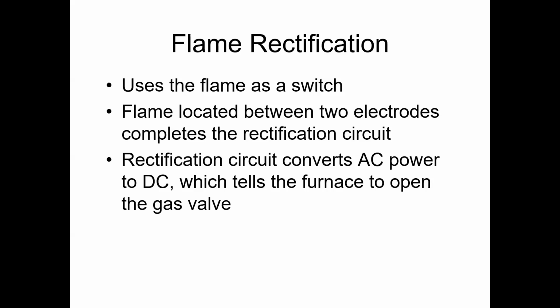These are used with HSIs. They're used with direct spark ignition. They're used with pilot systems, intermittent pilot systems. This is just the newest way that we have to prove a flame is currently working and operating as it should be. So the flame is going to be the switch.